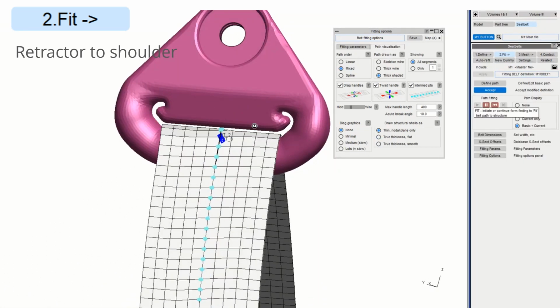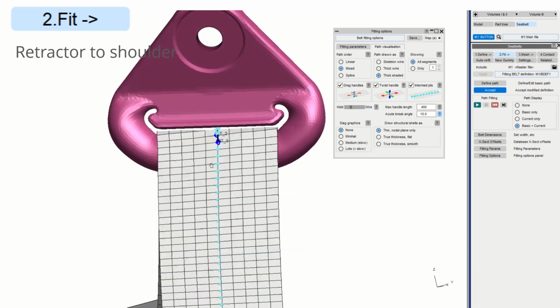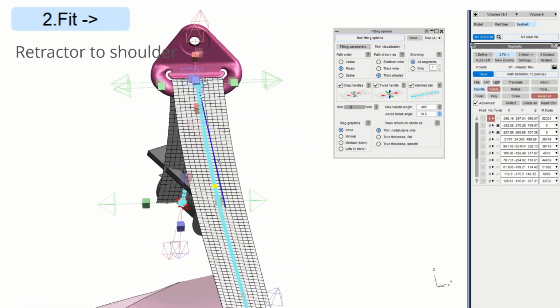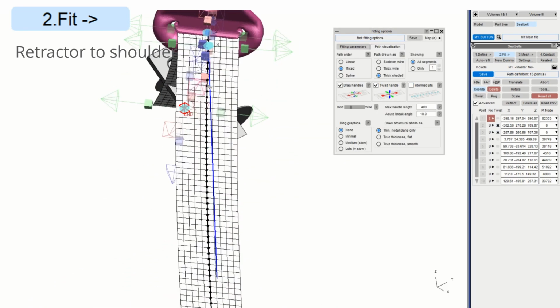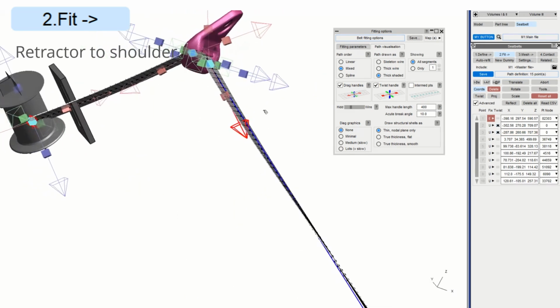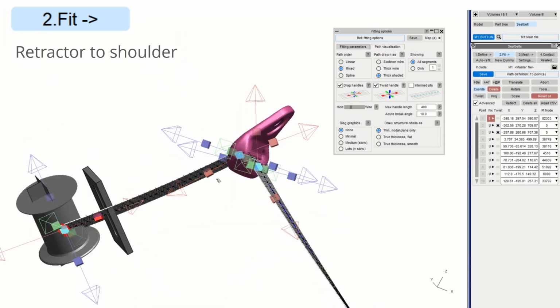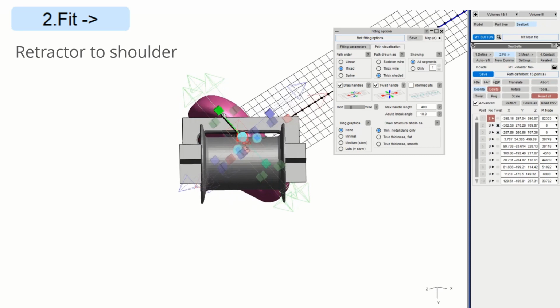We'll just save and do a test fit on that. Yeah, no problem with penetrations there. Now we can go back to the retractor and then just fix that. I'm sorry, we're going to look at the belt, set the belt angle coming in and out of the slip ring first of all, just to make sure the belt aligns with the next 2 points.